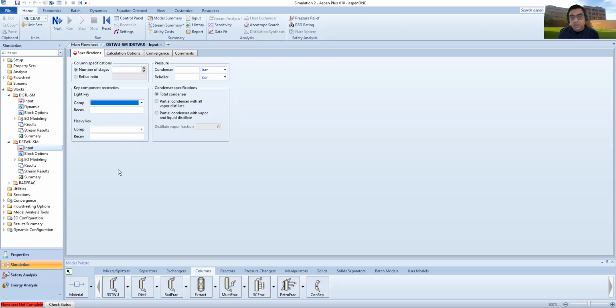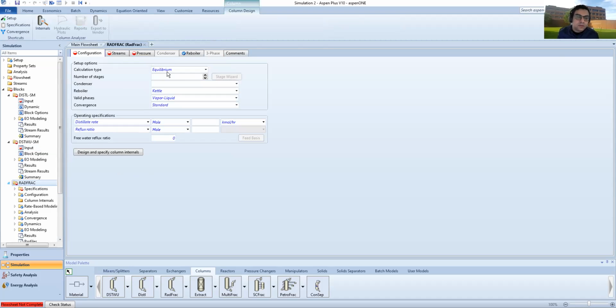They're not identical; they're designed for the different types of information sets you typically have when looking at distillation columns. Third one is RADFRAC, and as you can see, there are a lot more details happening here, right? The calculation type: you want equilibrium or rate-based. Rate-based is non-equilibrium. You see now we're looking at transient calculations, more complex design. Unlike equilibrium, McCabe-Thiele is equilibrium. You assume a constant molar overflow, everything is nice and cute. Now we're looking at more details.